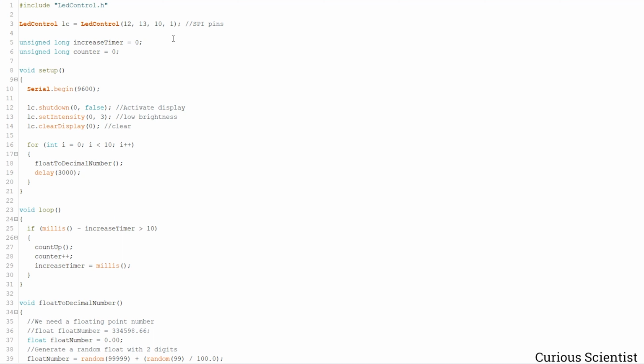And now, opposing my general practice, I define most of the variables at runtime inside the code, inside the functions. And here I just use a few variables for the timer and the counter. So you will see the rest of the variables later. What this timer does is just help us count the elapsed time, following the counting up inside the main loop. And the counter is just the counter which we increase by 10 every 10 milliseconds.